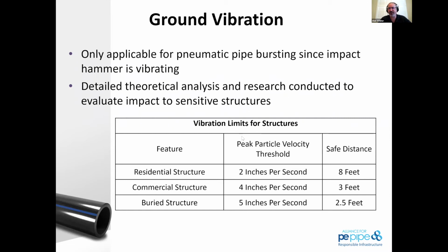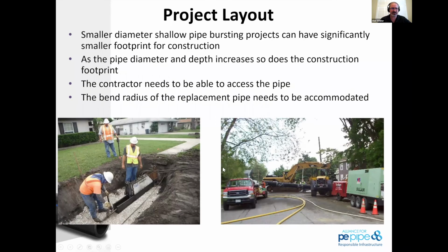One of the things about third-party utilities, especially fiber optic, which was a question that was answered earlier: if we know where those crossing locations are, a contractor oftentimes can remove the soil so there's no conflict of soil displacement. So potholing those utilities is often very important.